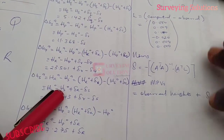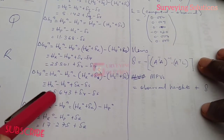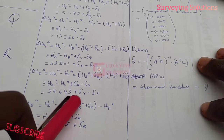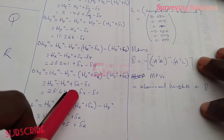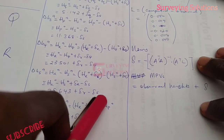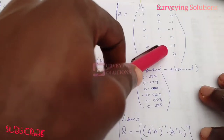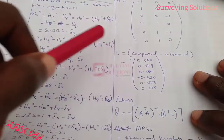We are just taking them randomly, but you should be able to get all of them at once. So now we have 28.643. Please, you need a calculator by you. So we have 28.643 plus, you see now we have R and S here. The R here is positive, minus the S here. So the R is positive and then the S is negative, which means there is no Q here for equation 5. You can see there is no Q, but the R is positive and the S is negative. So that's how you form your A matrix. Are we together? Now let's come to our L matrix.